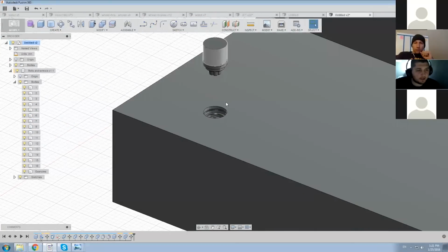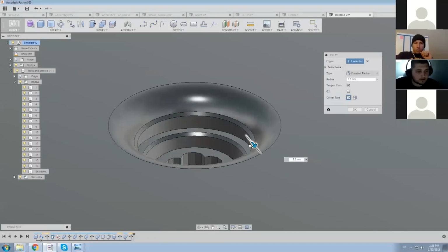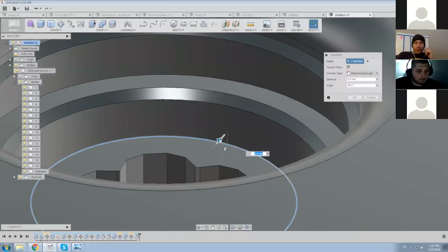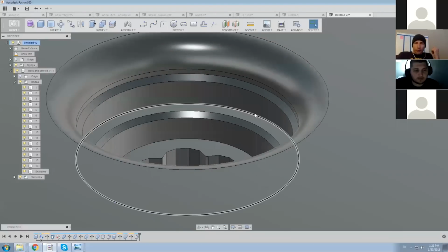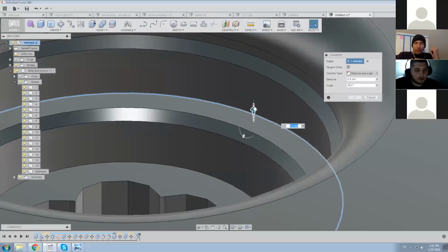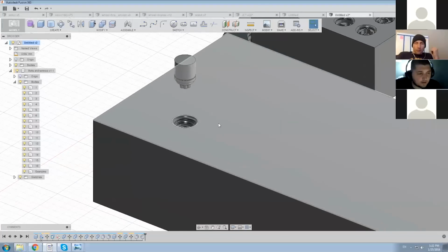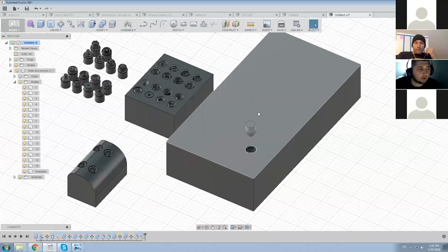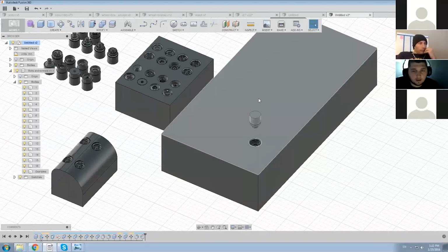Plus, after I commit, I can keep adjusting it like this, and I can keep working on it and making it better. You can add bevels to any of those edges, or chamfers as they call them, I guess. Yeah, it's in here, it's called chamfer and fillet. But you can absolutely change everything, so it's not set. Most of the time, all of the modeling trickles down to two Boolean operations: joining and cutting.